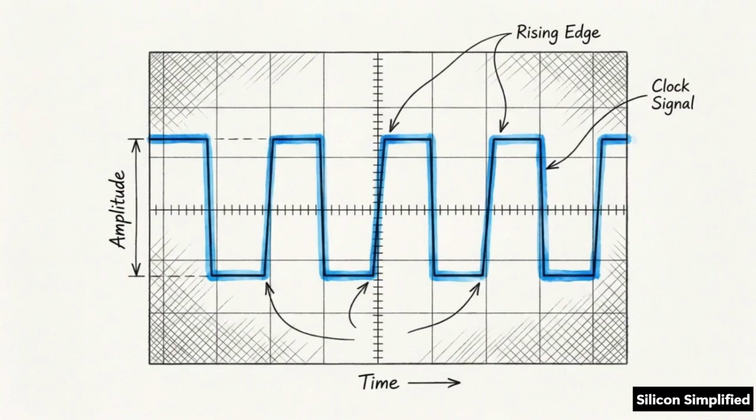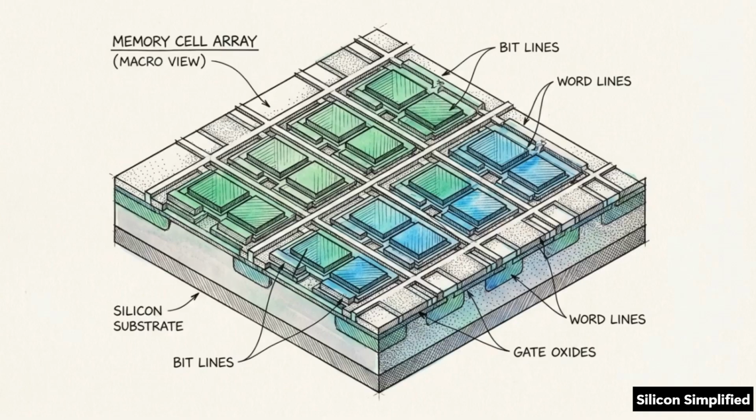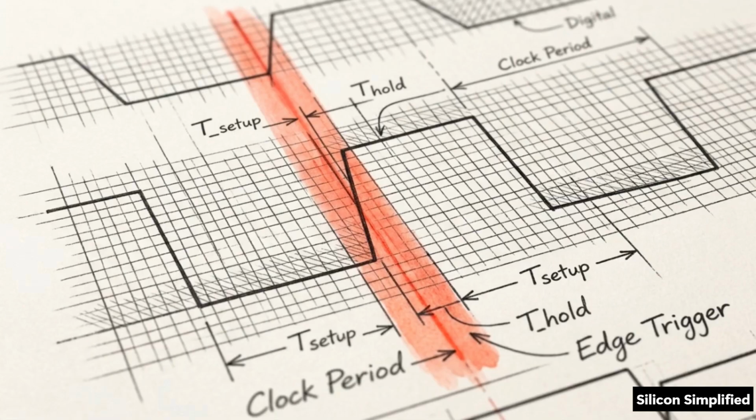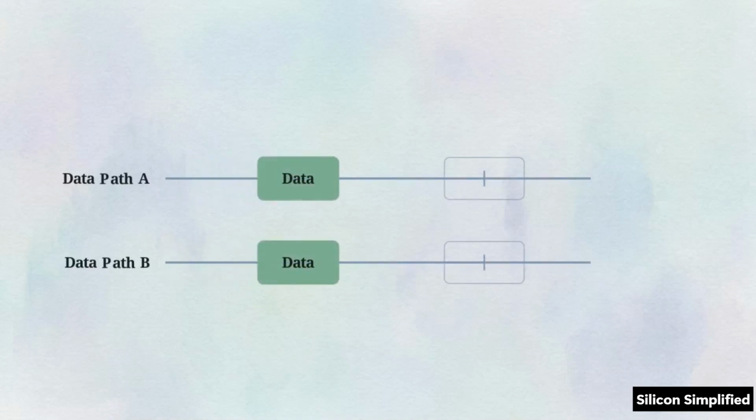With the logic mapped, we shift focus to the sequential block, triggered by the always at posedge clock syntax. This block governs the actual physical memory of the hardware. Its core action is simple. It transfers the newly evaluated next state into the active state register, executing this strictly on the rising edge of the system clock. To perform this safely, you must use the non-blocking assignment operator, written as a less than sign followed by an equal sign.